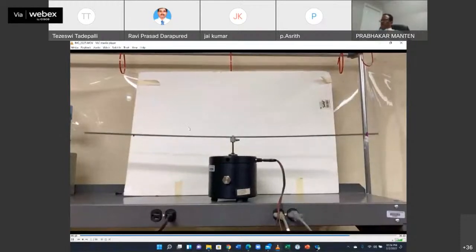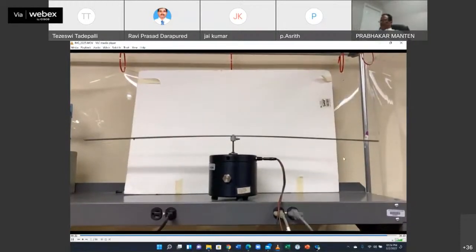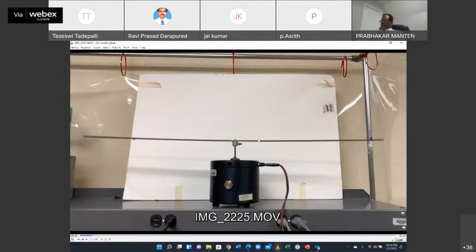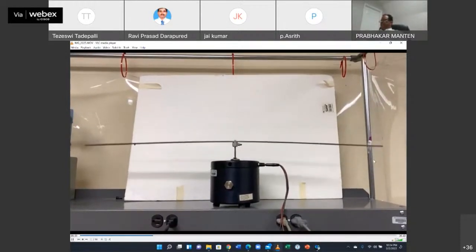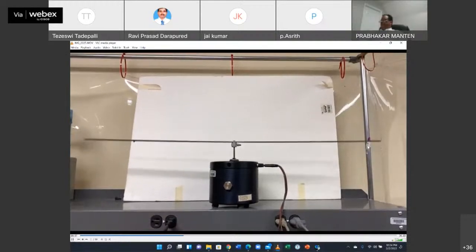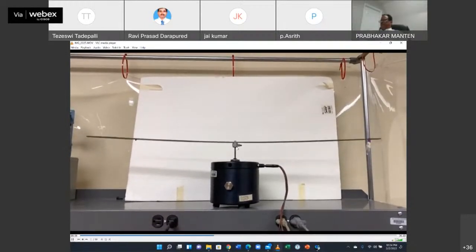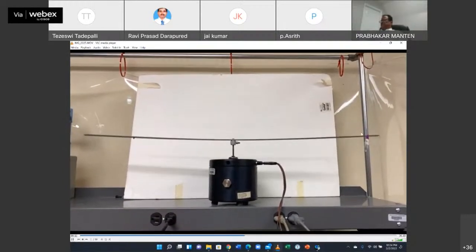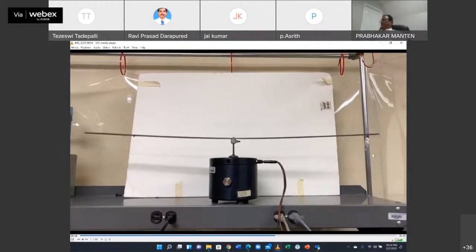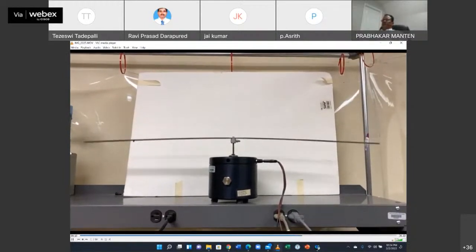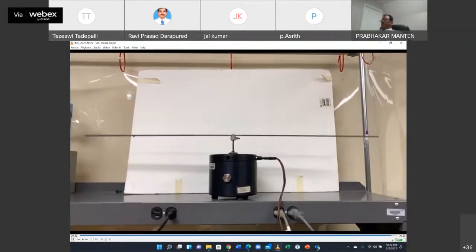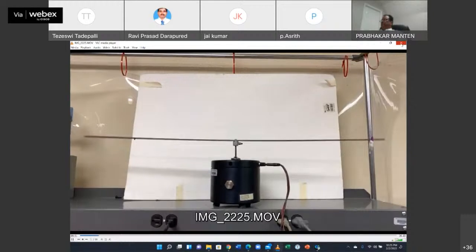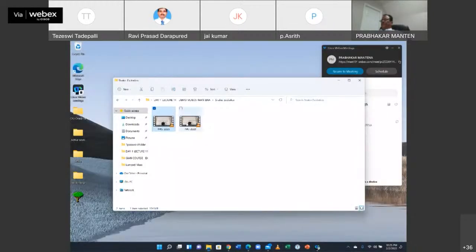We also have a stroboscope. When you know the frequency and match it to the frequency of the strobe light, you'll see this whole picture very nicely as if it's static. Slightly move the scope away from the forcing frequency, which I believe was around 670 hertz or something, then you will slowly see the extreme ends. So this is fundamental frequency oscillation, with the forcing frequency coinciding with the theoretically calculated one. So let's go to the second mode shape of the same one.